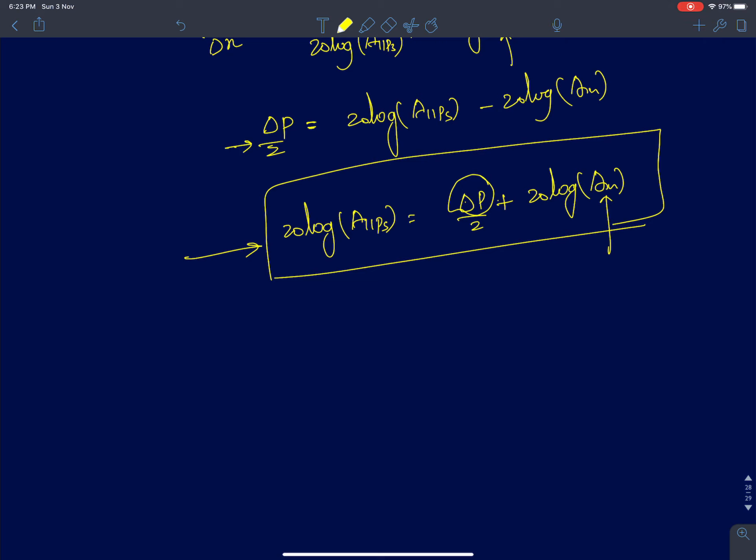With just the knowledge of this and this, I could easily calculate the IIP3. So this is a very, very useful approach, especially for hand calculations, where somewhere you have to start your calculations. So this is a very useful simulation for that. A first cut analysis, a first cut estimate of the nonlinearity, can be provided by this result.